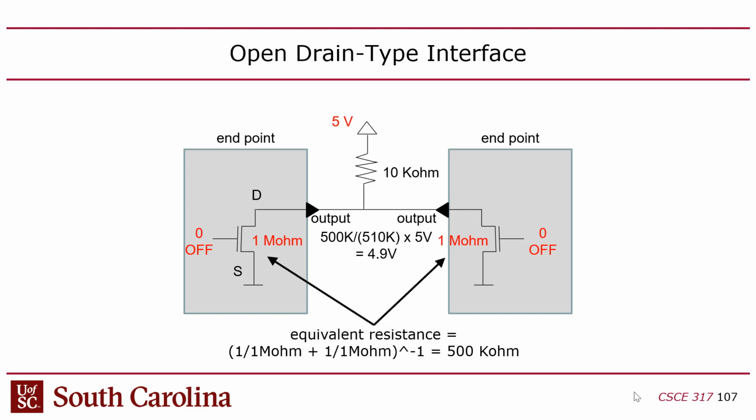You guys with me? Okay, now let's say, oh, and by the way, the leakage current through there, I mentioned there's a voltage drop. That also means there's some leakage current, but it's only about 10 microamps, right? So in other words, even if you have devices on this open drain. By the way, the reason it's called open drain is that